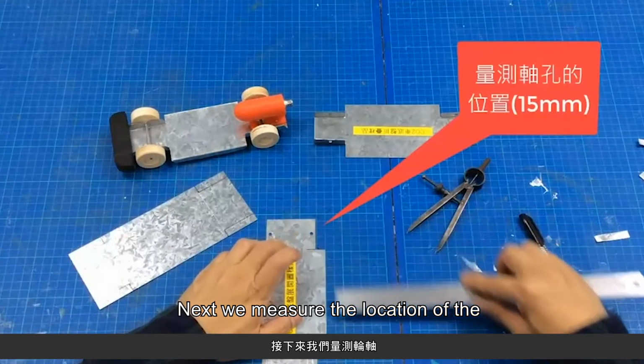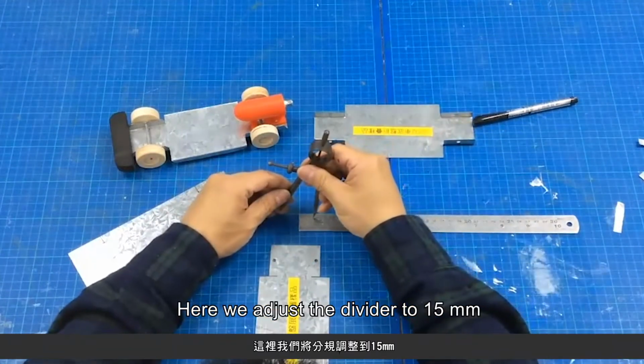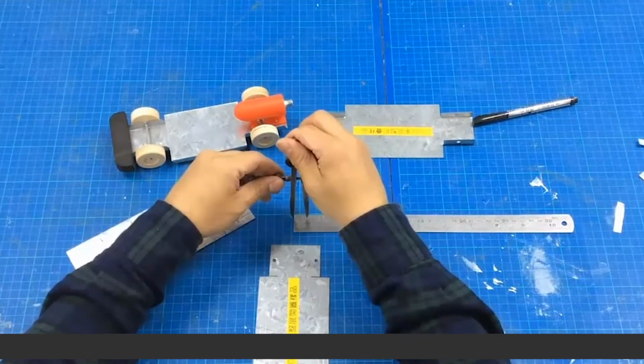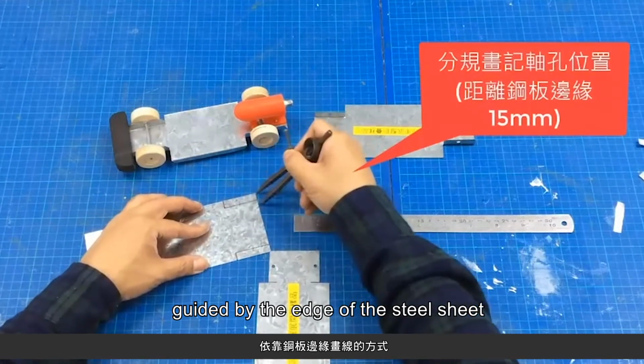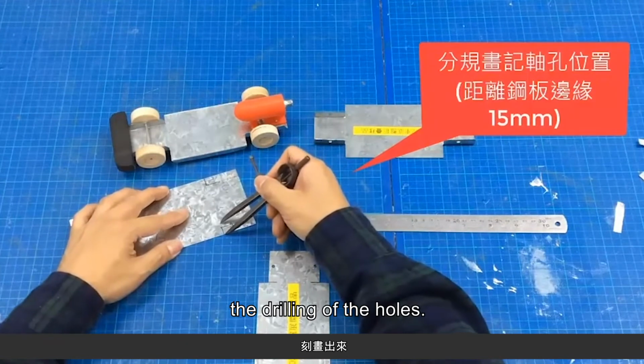Next, we measure the location of the holes needed for the axles. Here we adjust the divider to 15 millimeters. In the same manner, we use the divider guided by the edge of the steel sheet to draw the 15 millimeter distance required for the drilling of the holes.